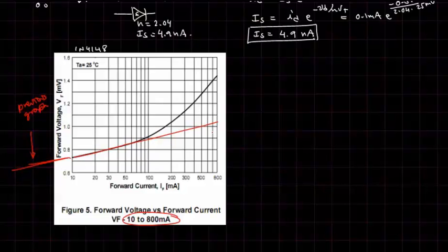And if we were to plot this on a linear scale, linear voltage versus linear current, you'd see that in this higher current region you would start to see a VI curve that was linear. In other words, it starts looking like a resistance. And so what's going on in this region here is due to ohmic resistance.